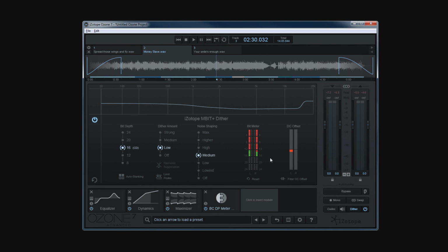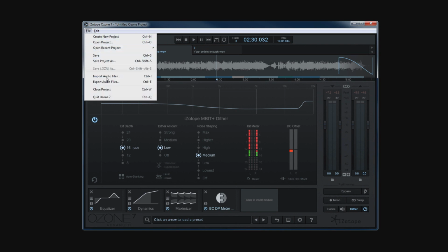Dither is low-level noise that is introduced by making the truncating process random. This has the effect of eliminating the ordered distortion, and hence the distortion that is present is less audible. Dither should only be applied once, only if reducing bit depth, and always as the last process of a mix. Adjust the settings here as required. The dither setting can either be turned on now or it can be switched on in the export dialog.